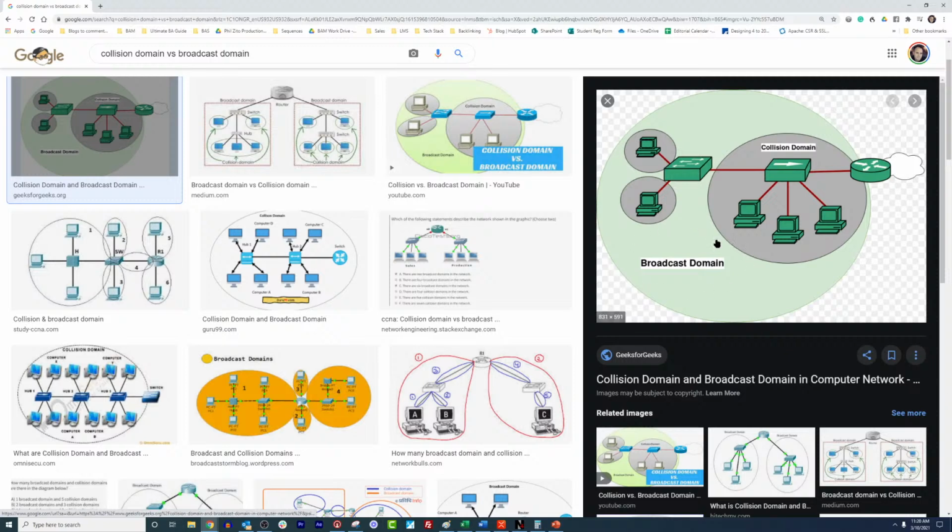We need to have one BBMD with a BDT, which is the BACnet distribution table, with entries for all of the other broadcast domains that we need to write to. Does that make sense, Joseph? Hopefully it does. If not, I'd encourage you to check out our BACnet bootcamp. But that's the simplest way, right?